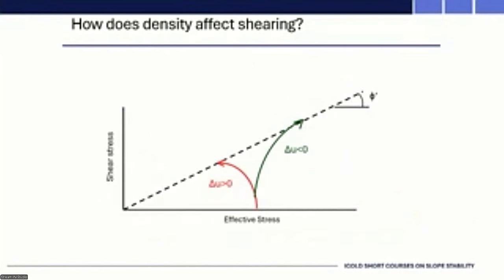Here, in terms of very simple stress paths, we've got shear stress against mean stress, or mean effective stress, on the horizontal. When you do a triaxial test, we apply vertical stress and keep the horizontal stress constant. We have a stress path that is essentially 3-to-1 in that space. That's the total stress path. But depending on whether we're dilating or contracting, it goes one of either way.